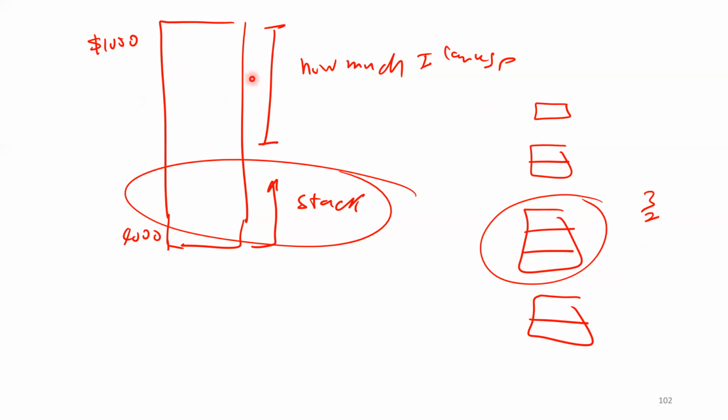So the way you should answer this question, for example, here you push, the stack was 1. At this instruction, the stack was 2. Now I push again, so the stack is 3. Then I pull, so the stack is 2. So look at the size of the stack over time, and you have to select the biggest one here. Okay. So for my stack, I don't need more than 3 bytes, because the maximum data that was in the stack at a certain point was 3 bytes. Okay, guys.